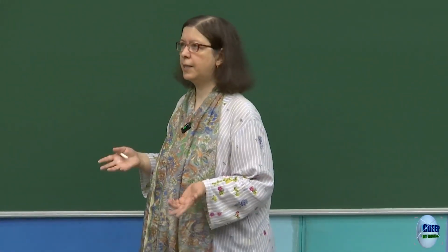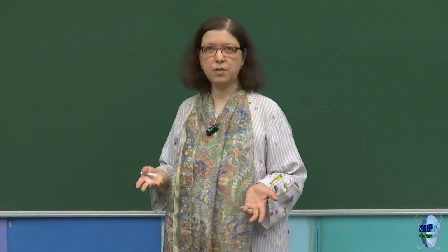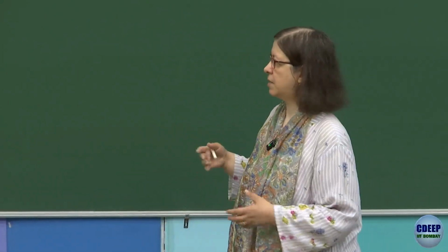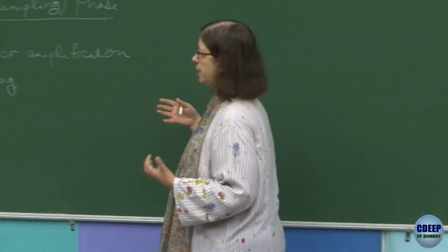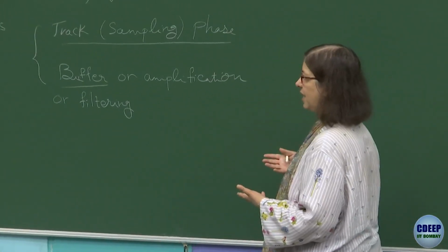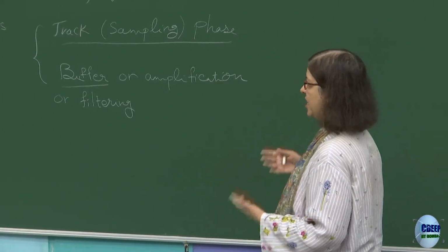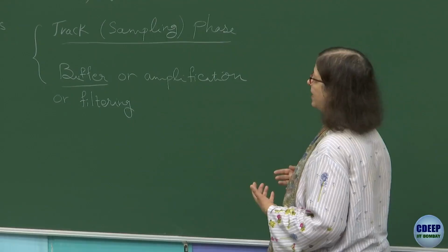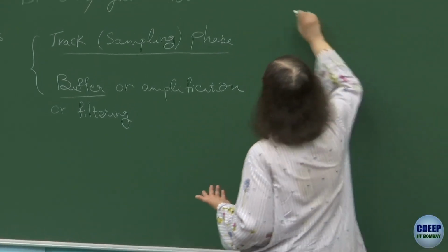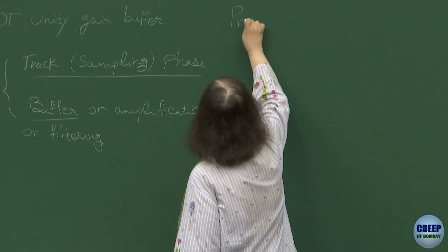When we talk about the speed, naturally we are talking about unity gain frequency, speed of the switches, settling time of the switches, and settling time of the circuit. So always we need to look at this too, because this is discrete time, and everything has to settle in every phase of the clock. And that's why we always look at the precision with respect to some corresponding LSB.